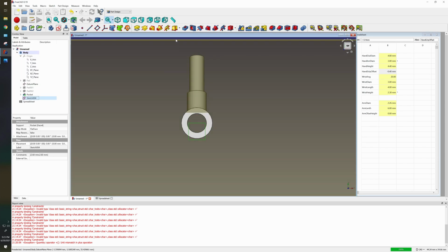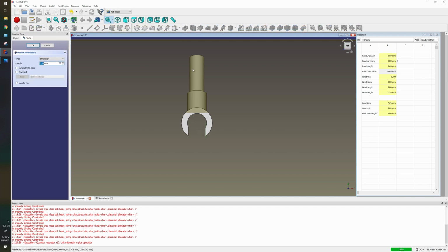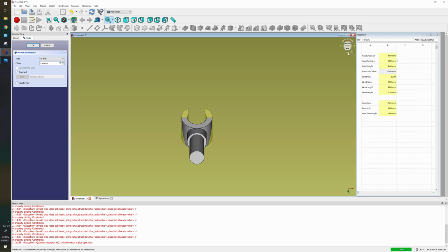and now of course we want this to be a pocket. Make it a pocket. We could give it a dimension. As I said, let's go up to first, hit OK. Well, look at this, nothing found in this direction. What does that mean? Sometimes you just have to reverse it. Face not found in that direction. Interesting. Which direction are we going into?